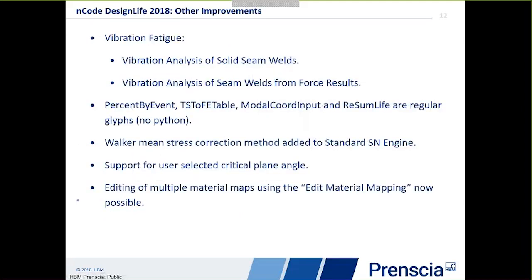We have quite a number of other improvements that have been going in. So these are a number of things in terms of vibration fatigue. We've added vibration fatigue capability, vibration loading capability, to most of the analysis engines now. And the last couple to add in terms of welds were the ability to do solid seam welds from vibration, and also the vibration of shell-based seam welds from force results. So this is completing most of the solver engines to be able to use vibration loads.